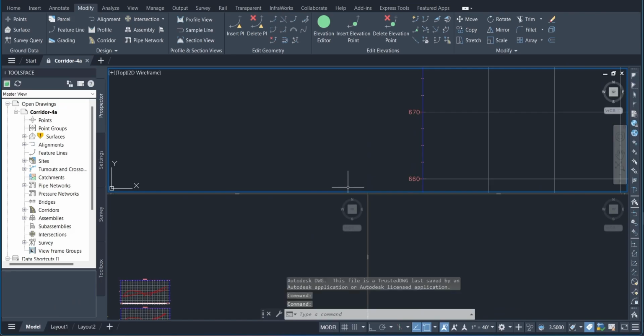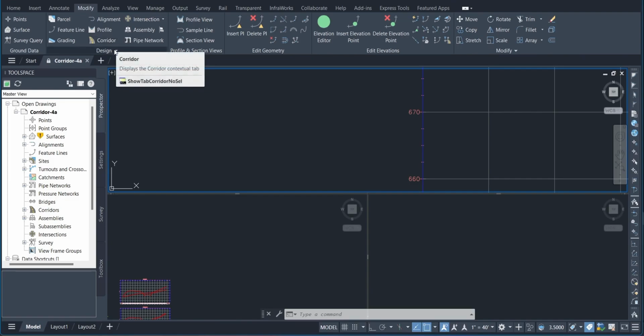In this exercise, you will view how a corridor assembly is applied at various stations along a baseline alignment. The View/Edit corridor section tools are useful for inspecting how the corridor assemblies interact with other objects in the corridor model. View a corridor in section.